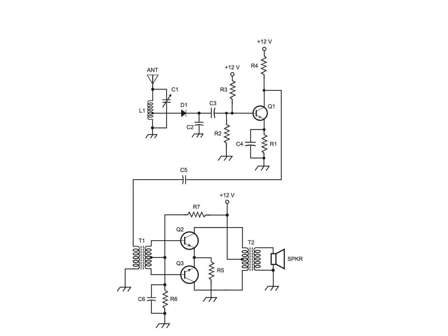This schematic is a respectably complicated diagram. It requires us to draw the system in a two-story format with the detector and preamplifier on top, and the audio power amplifier on the bottom. A long, tortuous line, broken in the middle by C5, represents the connection between the preamplifier output and the power amplifier input. There's nothing technically wrong with this diagram, but some people might rather see it all on one level.